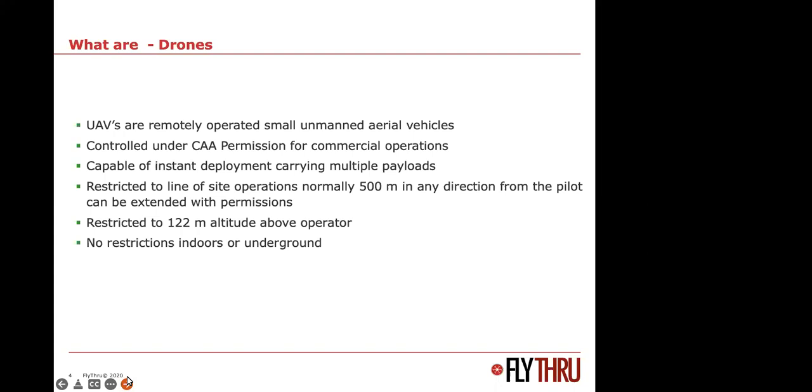I can guarantee that some of the drones that you are able to buy commercially now out there, you will not be able to see. If you can't see it, you're not allowed to fly that far away. Just because it says in your license you can, you cannot. You must be able to see the drone at all times. There are exceptions to that.